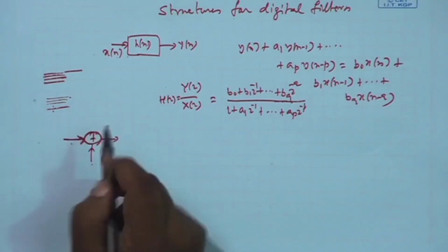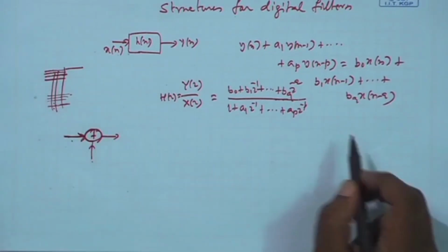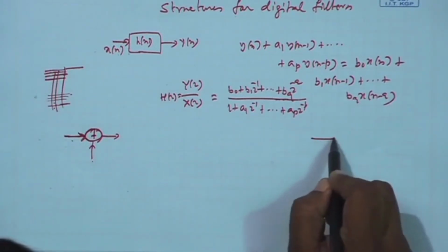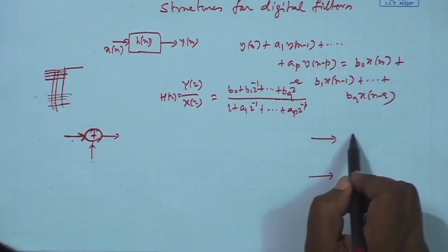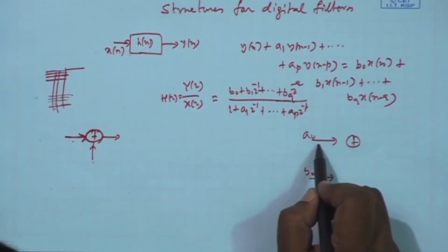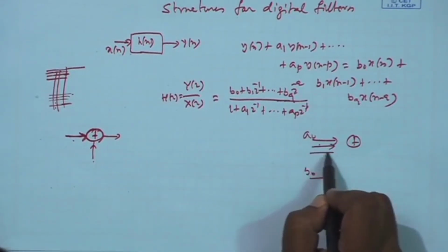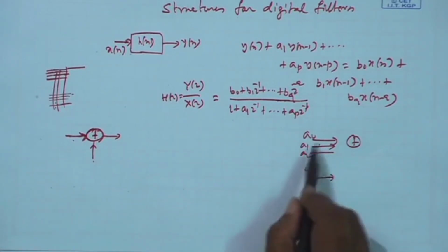The array of full adders is that kind of adder. In terms of digital electronics, it is like this. If this is the LSB of one data and the LSB of another data, suppose it is A 0, B 0. We have A 0, A 1, A 2, 3 bits consisting of one word or one bus.